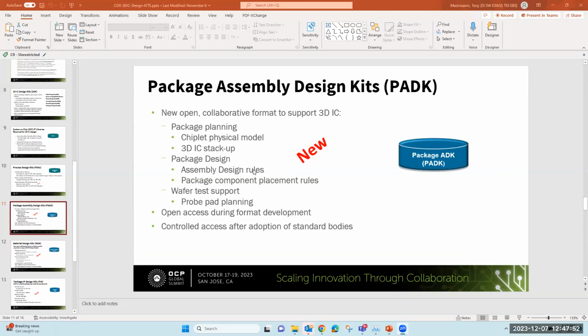For here, these are the assembly design rules. So these are the rules for placing your connectivity components, your bumps, micro bumps, how far they need to be away from corners, what the density of those is, and these are all min-max. When you transition your arrays, there are rules for that.